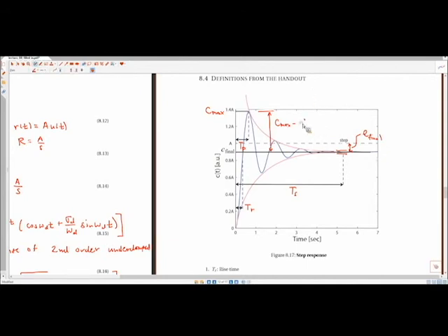Underdamped systems always have a zeta between 0 and 1. So on every exam or test from here on out where this is required, you'll have this map, and this is sufficient. If you say an overshoot of 50%, you would carry this over and say that is a damping constant of approximately 0.22, somewhere in that range, 0.21, 0.22. So this chart is going to fill in for that equation.